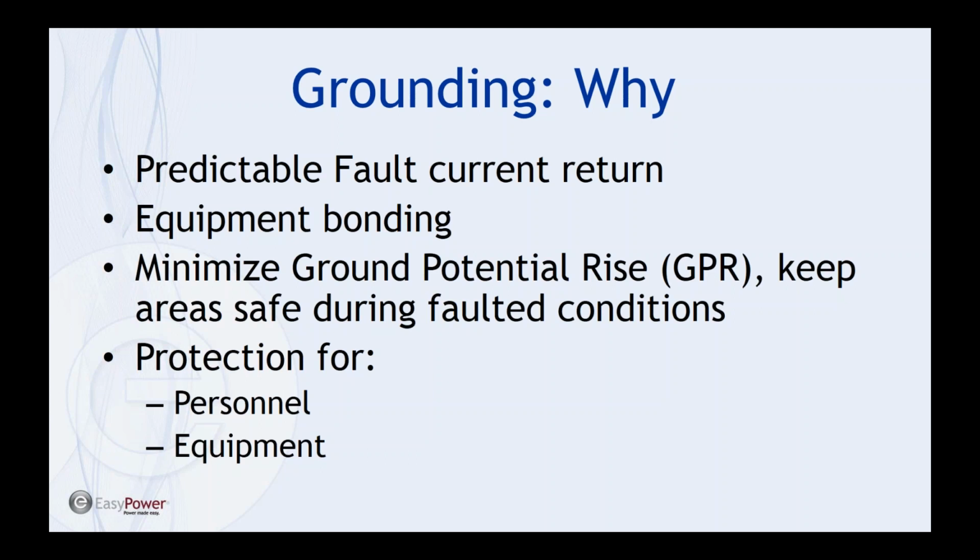Low resistance ground grids, more copper in the ground, or a ground grid that's well designed can help keep local ground potential rises lower, which can help with step and touch safety, but it also helps provide a low resistance path for voltage surges such as lightning and transients.